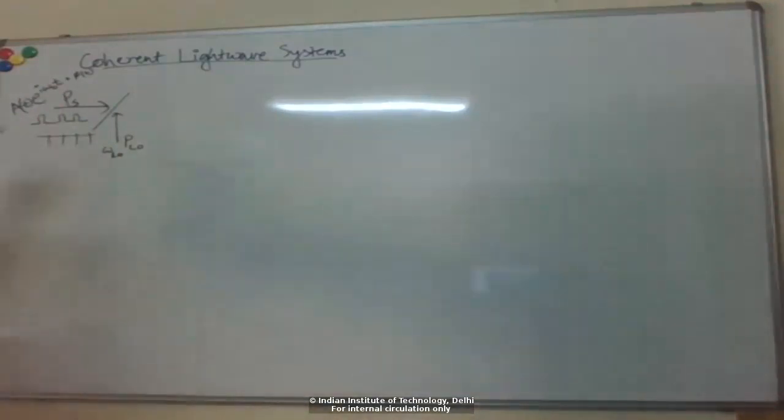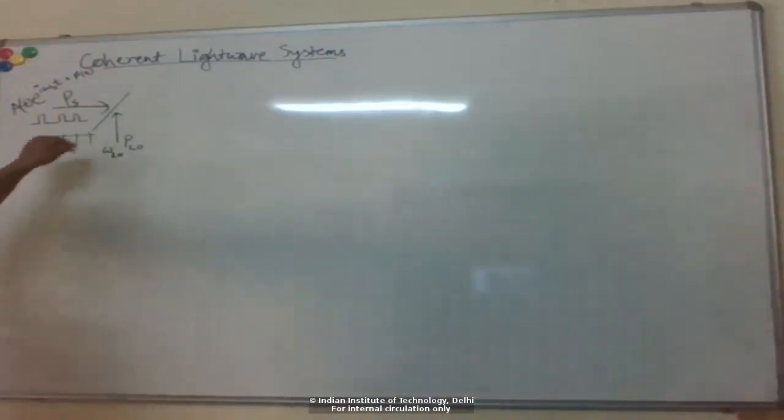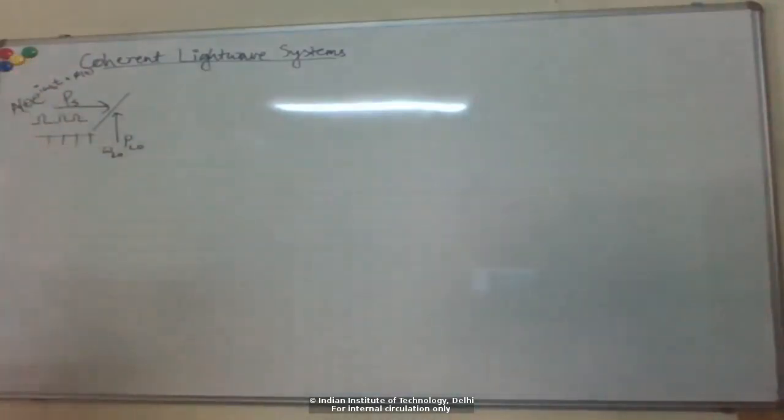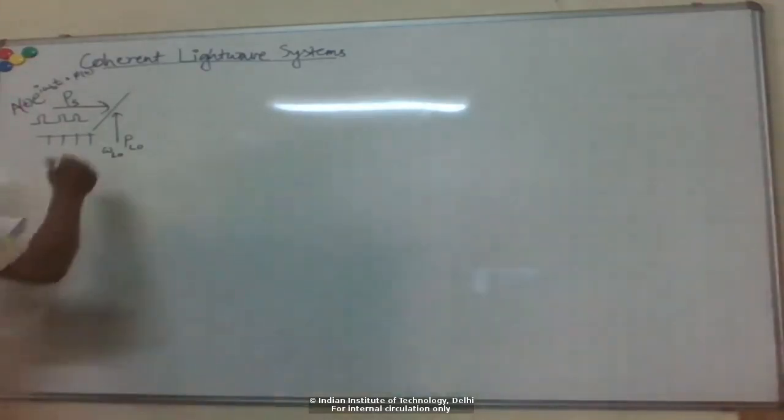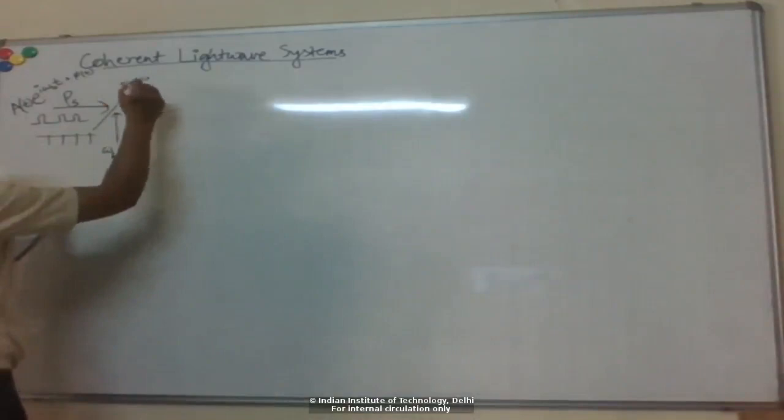Okay, you know, omega naught, the absolute frequency, is in hundreds of terahertz, right? So the difference between this local oscillator at my receiver and the carrier of the incoming signal is typically a few gigahertz, maximum maybe tens of gigahertz. Okay, so we beat these two on a beam splitter, typically a 50-50 power splitter.